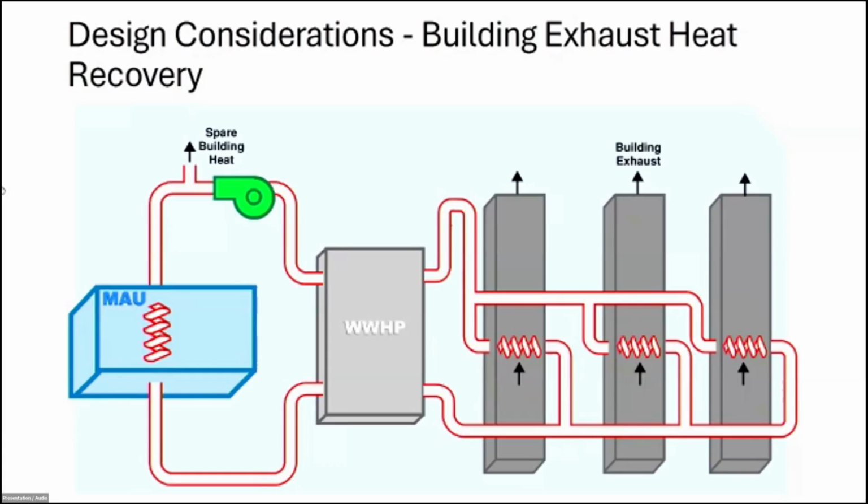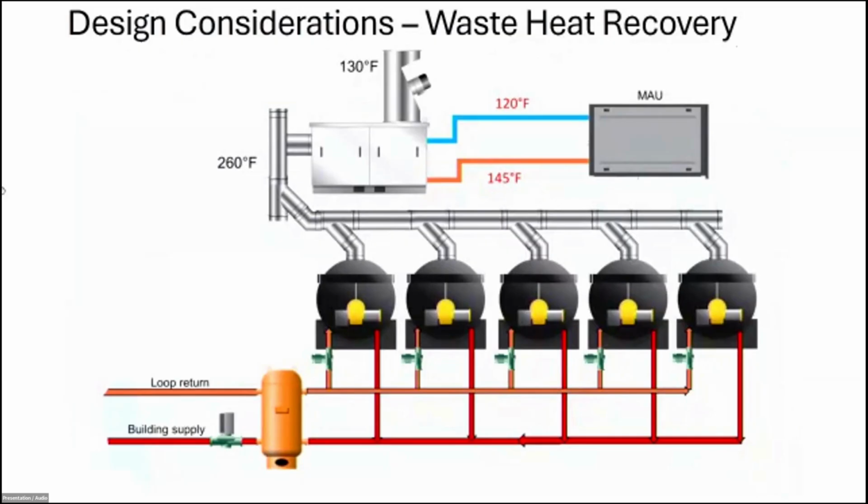This is the Enervex design that we have put in front of them. And what this centers around is their current water heating system. This is the system that is tapping out on the coldest design days, right? It's located in their basement. All of their flue is commonized into a single trunk line, and it penetrates from the basement, comes up through the building, and penetrates through the roof. What's located 20, 30 feet away in a penthouse? That makeup air unit that is running out of heat on those coldest design days.